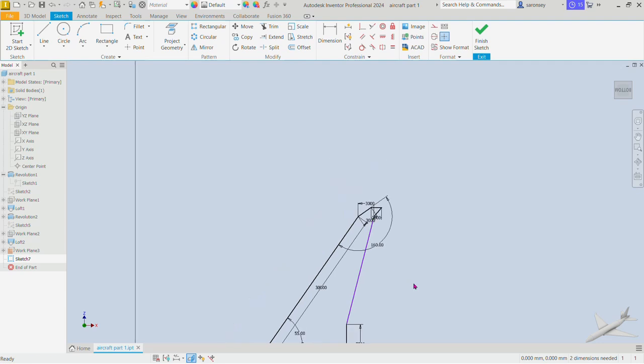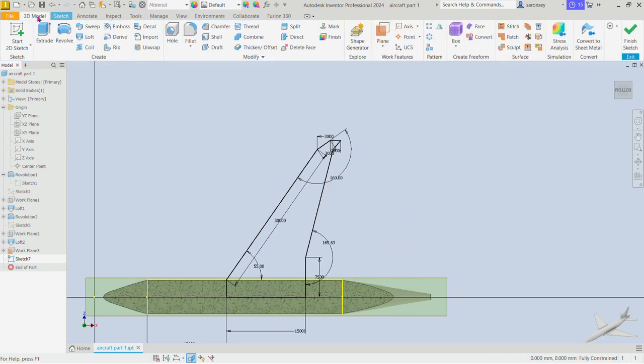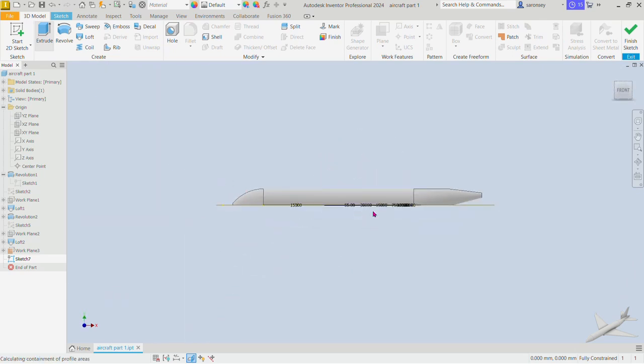Now let's put an angle to fully constrain the sketch. And so dimension, let's do this line and that line and go with whatever dimension we are getting. Check that. Now we'll pick the line command. Let's close this up. We can extrude now into 3D, command extrude option.